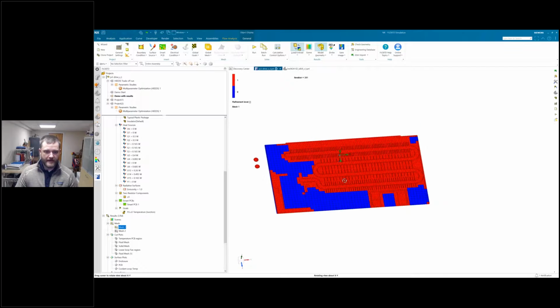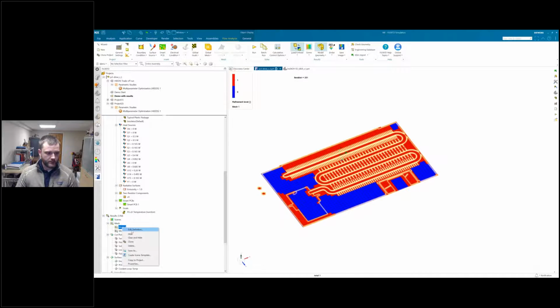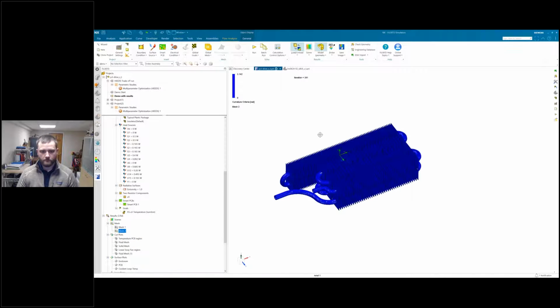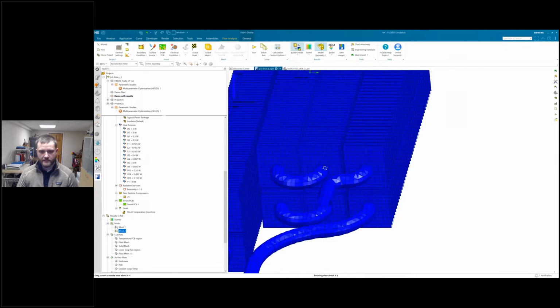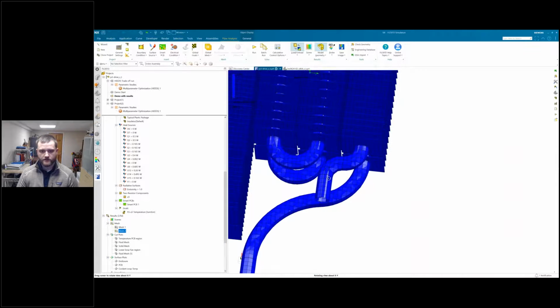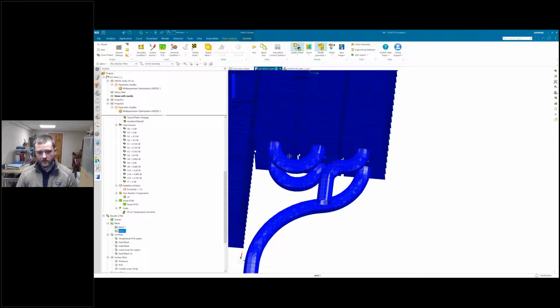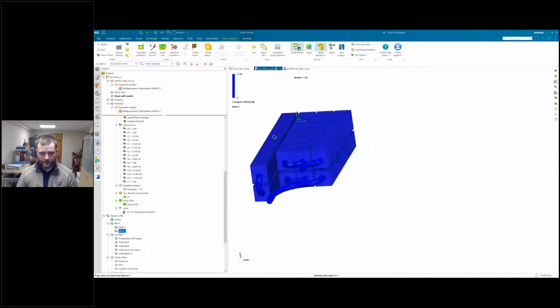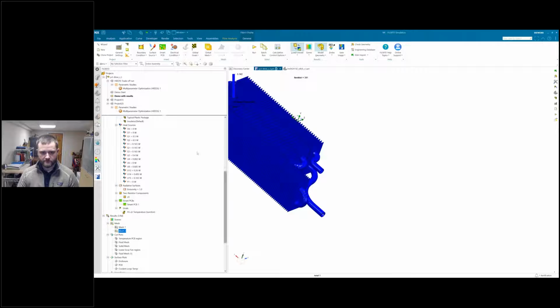So that shows that. And then if we jump over, we want to look at the mesh on the actual solids, what it looks like. We can show the mesh. This is what the smart cells look like, where it's subdivided cells, and these are smart cells that are shown on the fluid solid interface here. And this can be made much finer depending on what level of fidelity you need. But for this case, of these type of pipes, this should be perfectly sufficient.